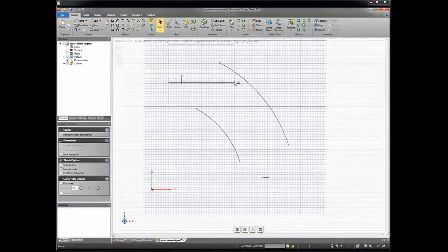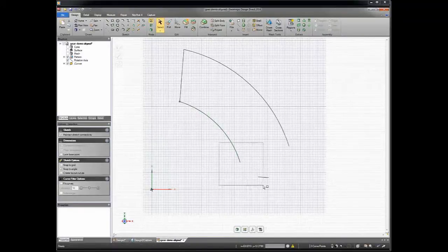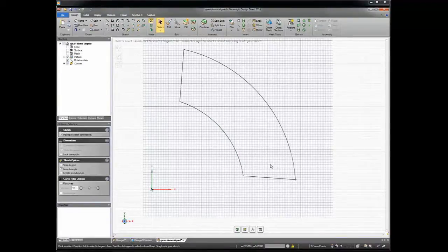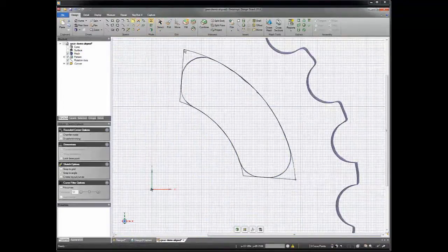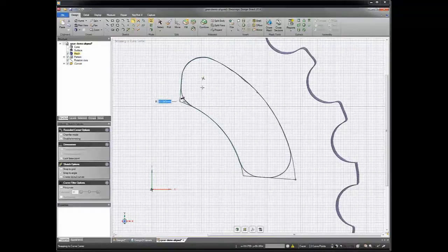If I use our select tool, you can really quickly just drag the cursor over it. It selects those two line ends, and then hit the F key, which is fill, and it'll fill those in. Another nice feature is if we go to our radius tool, you just click this corner, drag it in, and it'll snap, as you can see there. It's almost like a little force field, snapping to that underlying mesh. I can repeat that on all four corners, and it will snap to the mesh.